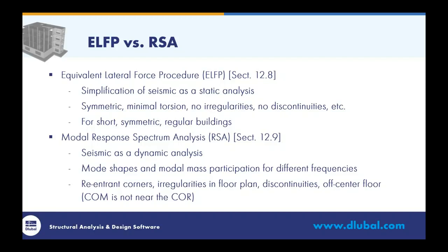And instead of running this simplified method, this is where we would turn to a modal response spectrum analysis. This is covered in section 12.9 of the standard. So this takes seismic considerations into account as a true dynamic analysis. We run our modal analysis to determine the mode shapes and modal mass participations for different frequencies of our structure.